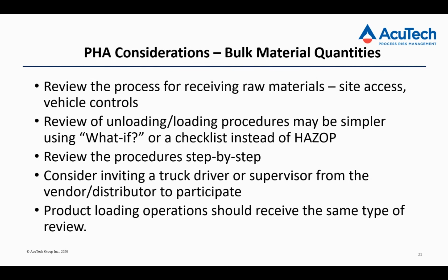And often it might be easier to use a checklist or a what-if approach for unloading operations than trying to shoehorn the unloading process into HAZOP deviations. After all, HAZOP really is just organized what-if. What if flow rate is too high? What if flow rate is too low? What if the flow goes someplace where it's not supposed to go? So a checklist can really help you, again, for consistency from unloading operation to unloading operation.